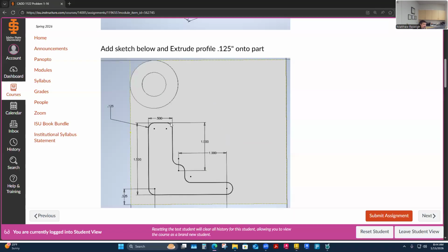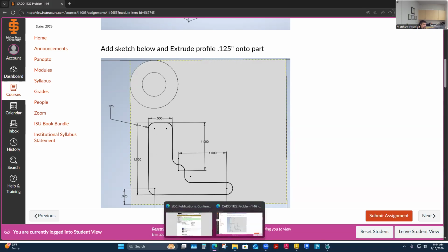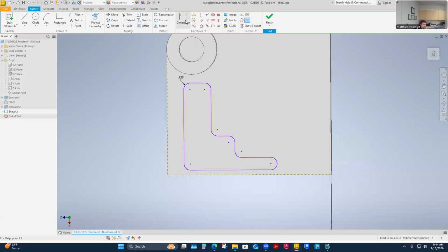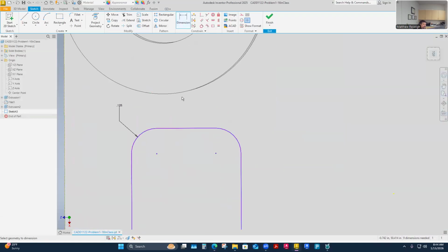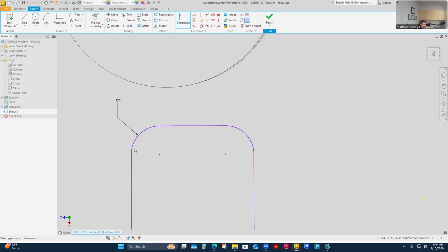What the heck is this thing? It's a 1/2 inch this way and it's an 1.5 inches this way. I'll do those two dimensional constraints, 1.5 inches by half. That means, and I tend to choose when I do line dimensions, I will tend to not choose the endpoints of the line as much as I will just the actual line to dimension to. Line to line here, I'm going to say is 0.5.